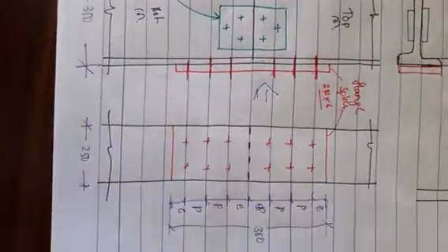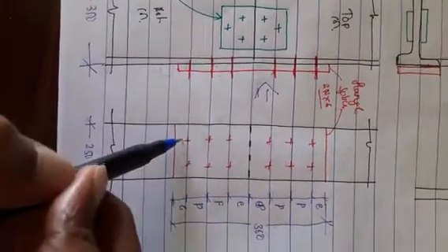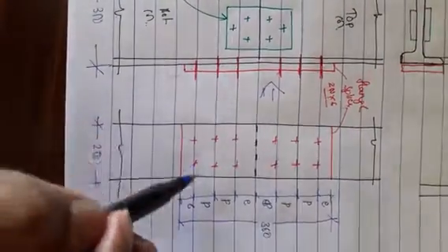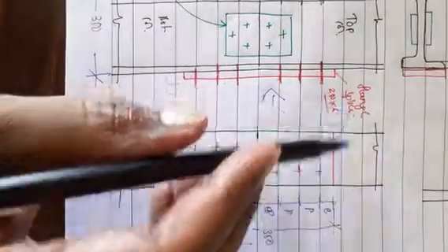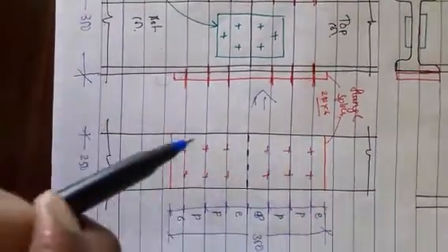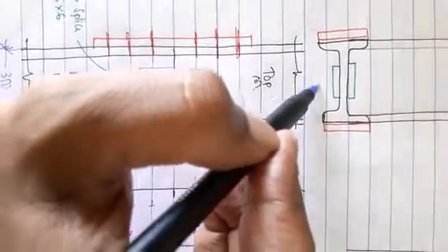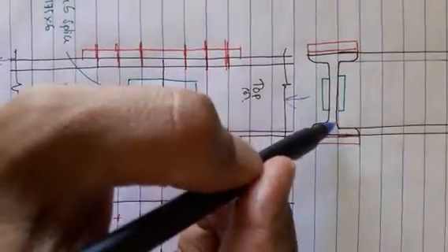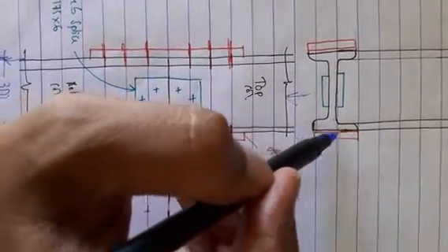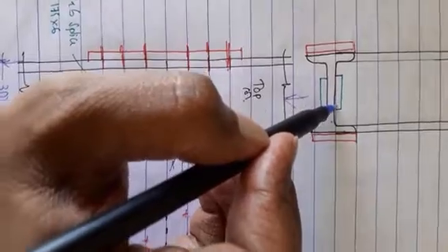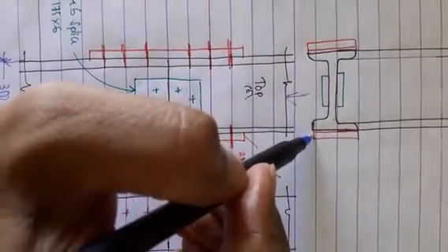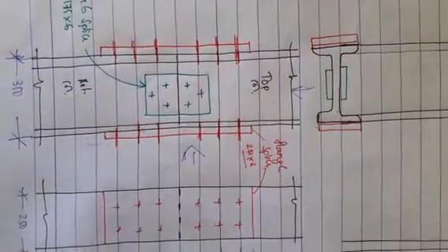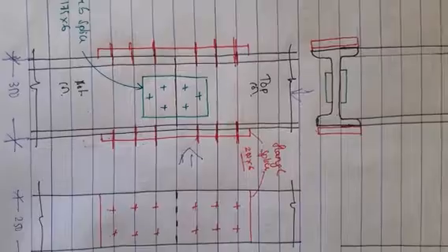This edge is seen here. These edges are seen here. This joint is seen as a dotted line inside the plate. Whatever this red line you are seeing is the flange splice, and these are the bolts. If you take a top view of this, this black indicates the I section, a flange plate on the flange, a web plate on the web. The width of the flange plate should be equal to the width of the I section. So this is a typical same size column connection.